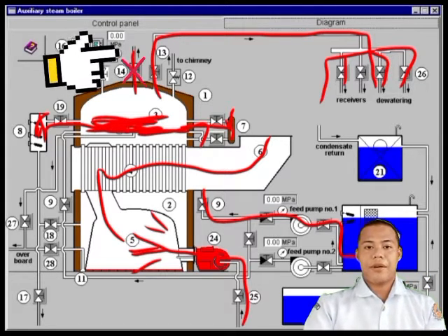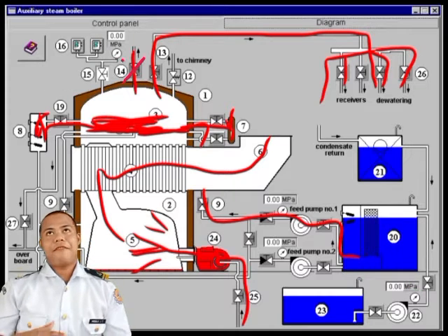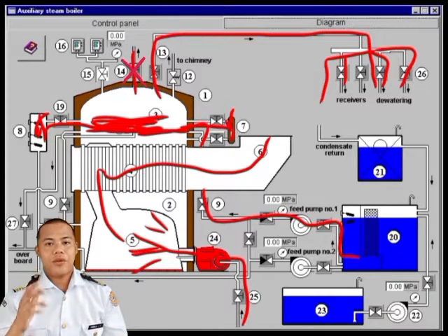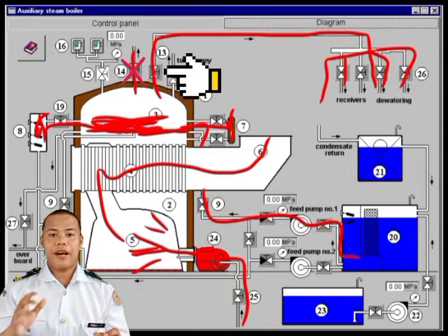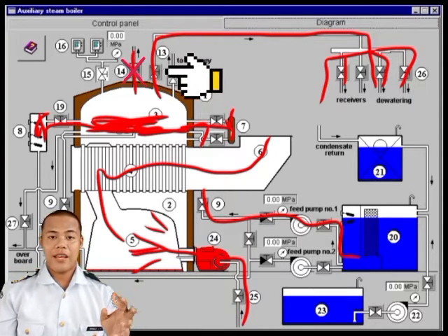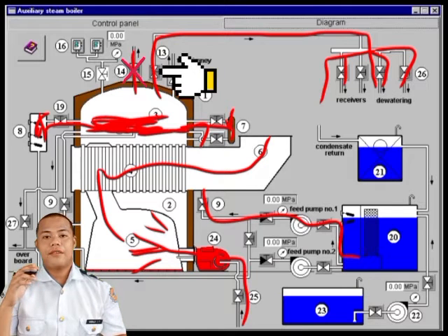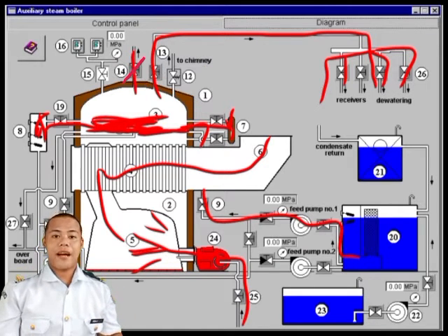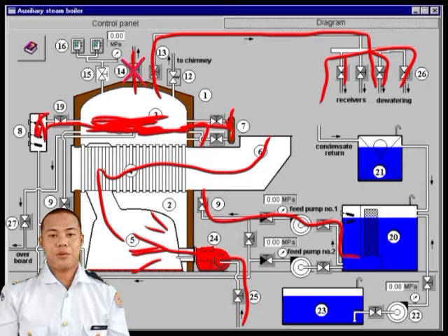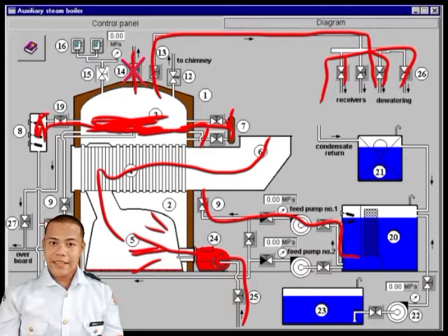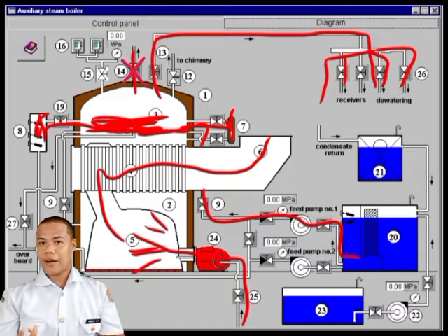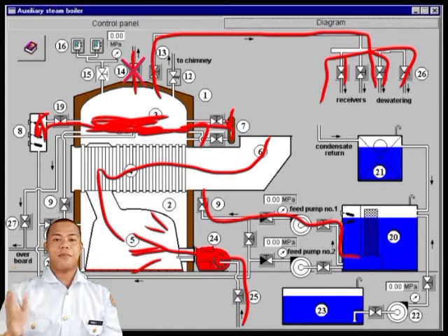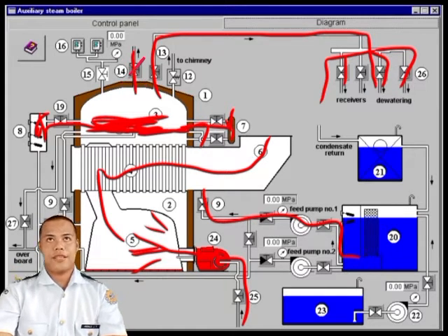in the pressure gauge. If the pressure is enough, then gradually open or turn the main steam valve to avoid thermal shock. So we open it gradually, and to prevent also water hammering as it goes to the consumer. So it can be seen in the side glass if the combustion is good, since the color of the fire is gold, and if smoke is visible, then the combustion is bad.